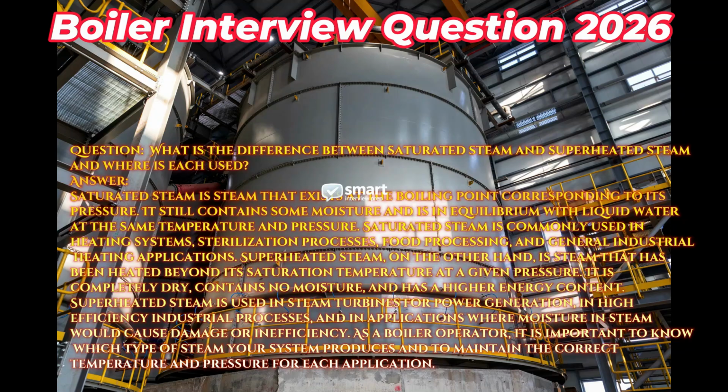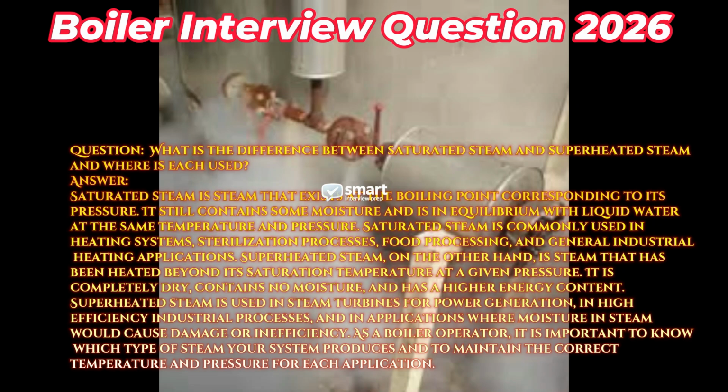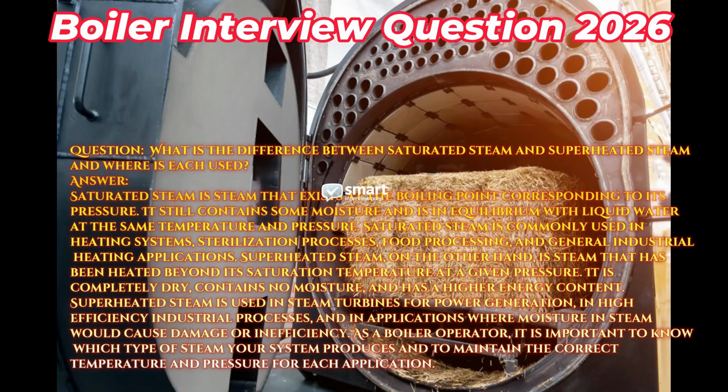Superheated steam, on the other hand, is steam that has been heated beyond its saturation temperature at a given pressure. It is completely dry, contains no moisture, and has a higher energy content. Superheated steam is used in steam turbines for power generation, in high-efficiency industrial processes, and in applications where moisture in steam would cause damage or inefficiency. As a boiler operator, it is important to know which type of steam your system produces and to maintain the correct temperature and pressure for each application.